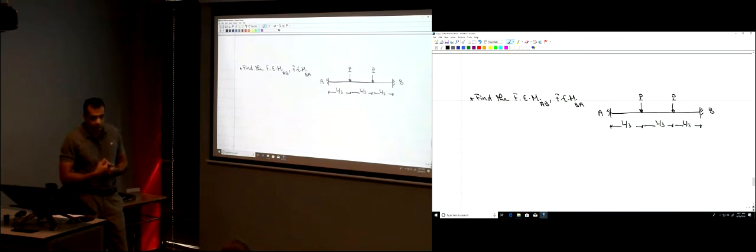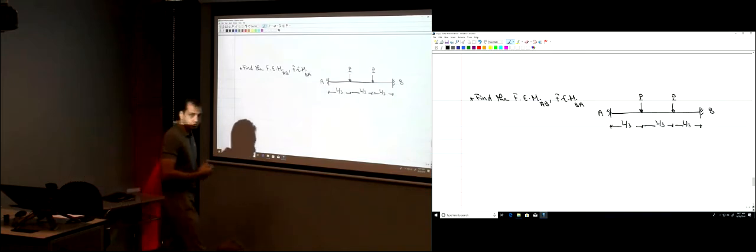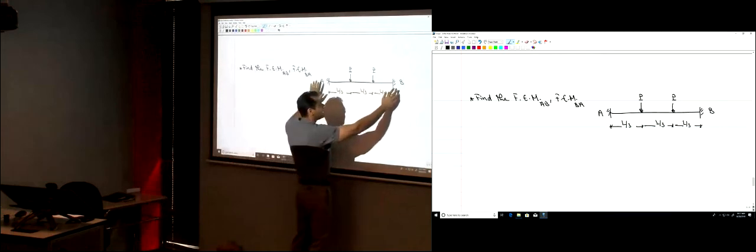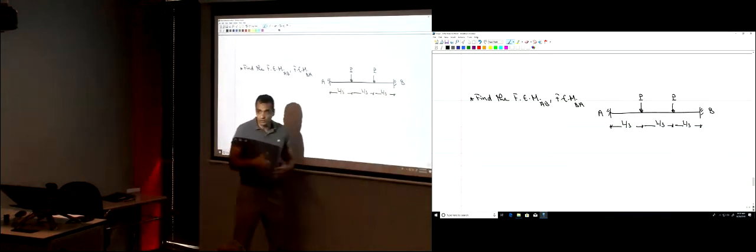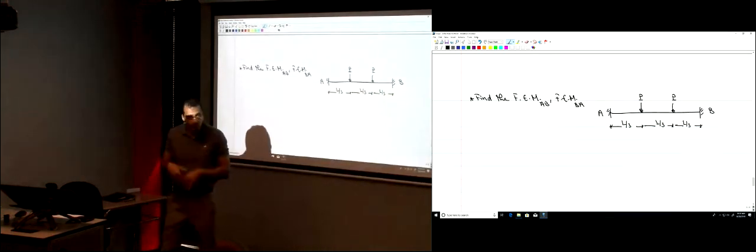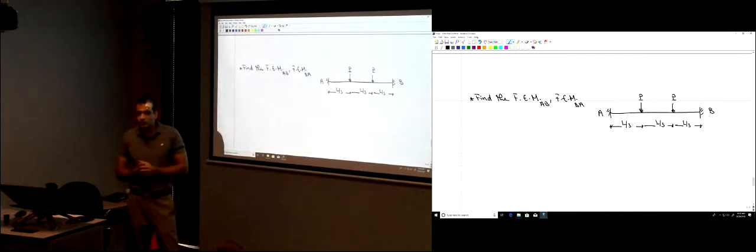Right? What you need to do is draw the bending moment diagram. Okay? There will be two parts. Part due to those loads, and part due to MA and MB, which are equal to each other. Just name them M. Okay? Put this on the conjugate beam. Study the equilibrium. Sigma Fy equals 0. You get that moment. It's that simple.